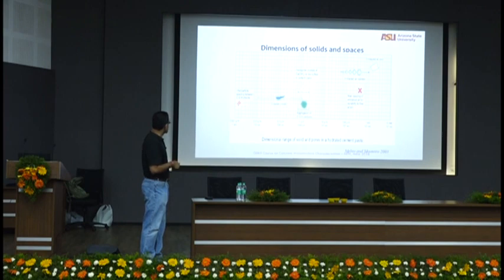The capillary voids, which might be 100 nanometers. CSH aggregation about a micron. Calcium hydroxide 1 to 10 microns. Entrained air bubbles about 1 millimeter, 10 millimeters.